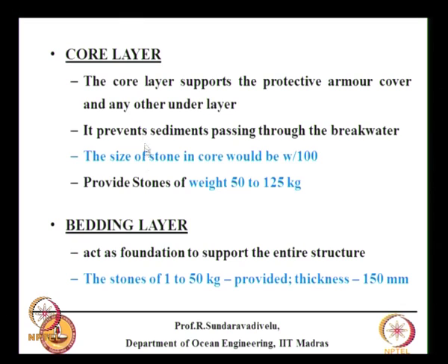So we were discussing that there are different layers. One is the armour layer, then we have the underlayer, then core layer, then bedding layer. We will see how to design the core layer. The core layer supports the protective armour cover and any other underlayer, that is, it is used as a foundation for the other layers. The other important thing is it prevents sediments passing through the breakwater.